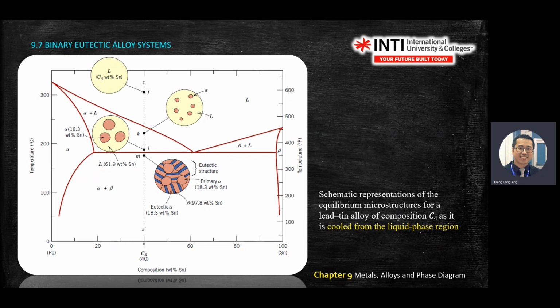So you get one temperature, and then identify where the solid is. On the left side you get alpha, on the right side you get beta. When you draw the line, you should be able to illustrate with the diagram. At the top, J is full liquid, and it passes through this region. At K, you start to have alpha and liquid, and if you drop lower, although in the same region, at point L, your alpha grows.